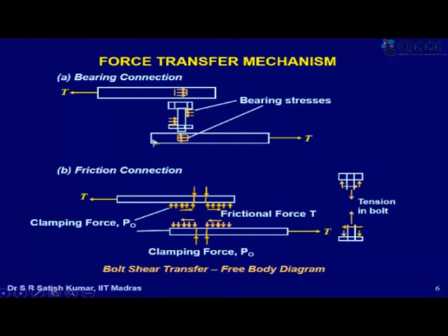But if you pull this, this plate actually bears on this shank of the bolt. These orange arrows show the bearing of the plate on the shank, and as a consequence, the shank in turn bears on the wall of the hole. If I am pulling this plate like this, my left hand is bearing on the right hand, but the right hand is also bearing on the left.